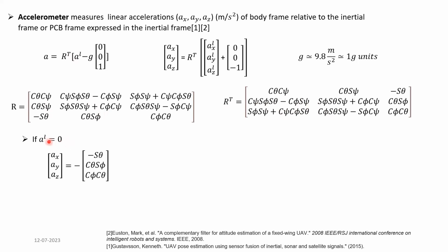So by substituting this R transpose here, we'll get it in this form, right, we have only minus sine theta. This vector we will get here. By solving these vectors, we'll get phi as roll, theta as pitch. Simply tan inverse. That means by just doing this, these two divided by, we'll get this. So something like that. We'll get phi and theta, roll and pitch.